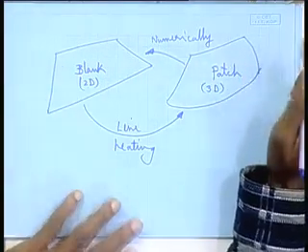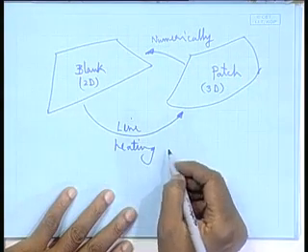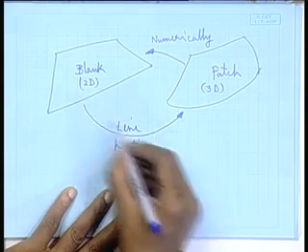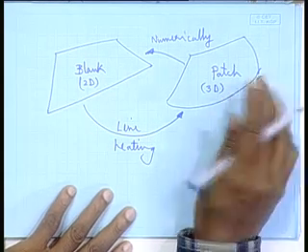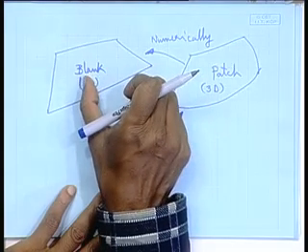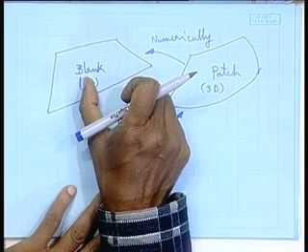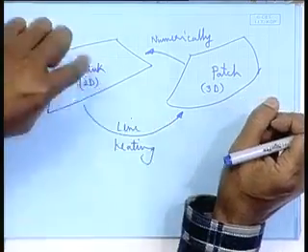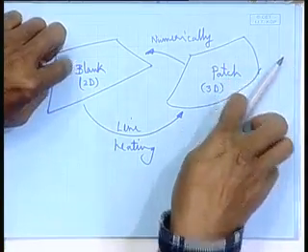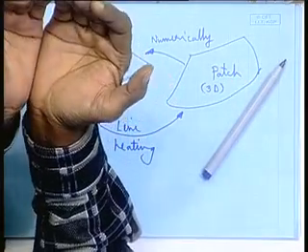So important is to get to the heating pattern. This line heating I will apply, and I will get that patch. So how do we get that? Essentially, when you are coming from the patch to the blank, what are we doing? We are taking out the strain which has been imparted in this blank, because I told you, when it is a doubly curved plate, from a flat plate you have to apply strain in it.